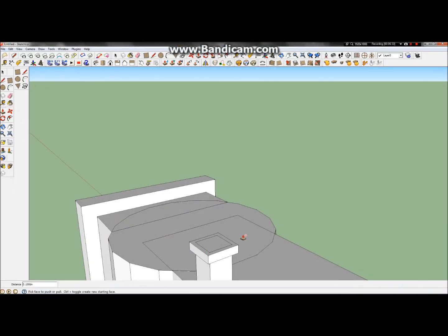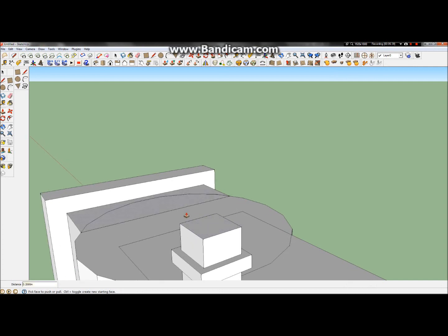Alright, so then this comes through about 0.2. And it looks like there's a little cylinder poking up here. Let's go ahead and put that in and see. I'm hoping there's going to be a little more detail than my last Jetway. Make sure you really bring down the sides, maybe 5 sides. So 5S, say enter. Let's go for 6 sides. And let's make a radius of, round it to 0.1 here.